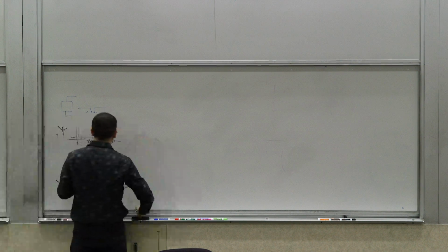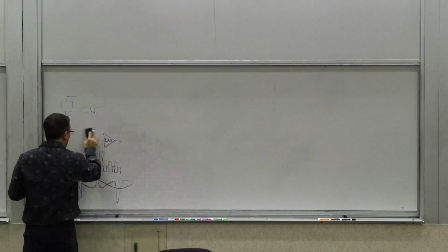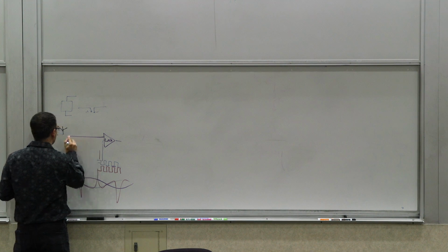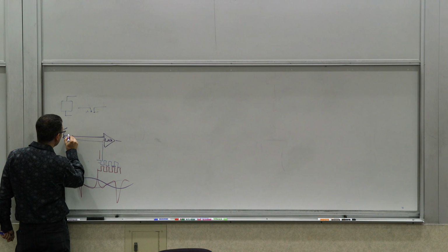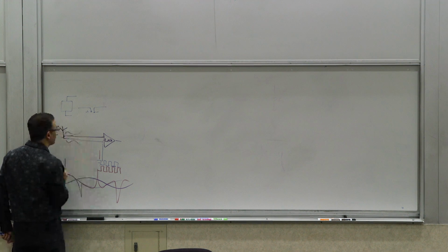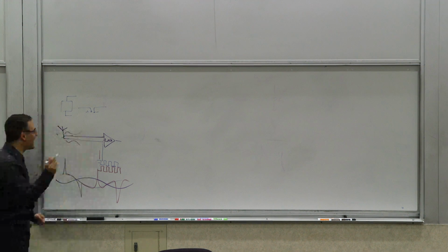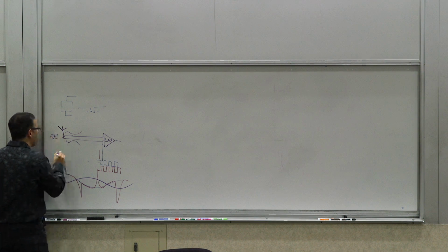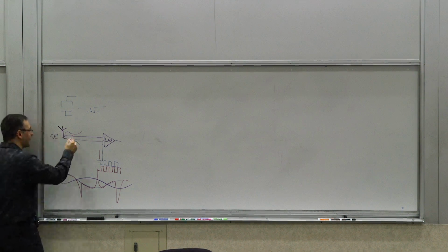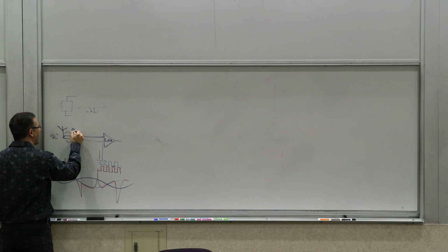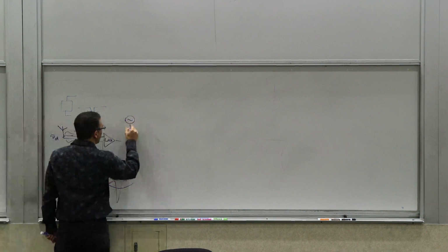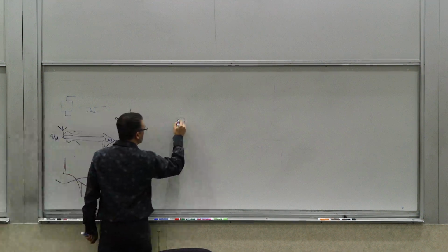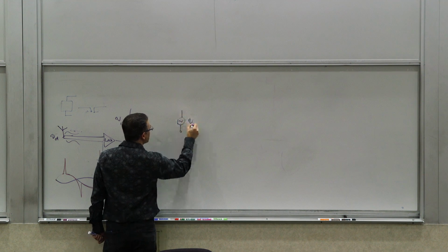So let's say now instead of doing this, we are going to have two lines. So my antenna is a differential one, and this signal has the opposite phase of that signal. So I take my signal, let's say Vin, and divide it into half in the positive phase. So I have what I call the VD, and I have two signals, let's say V1 and V2, whose difference is what I'm looking at.